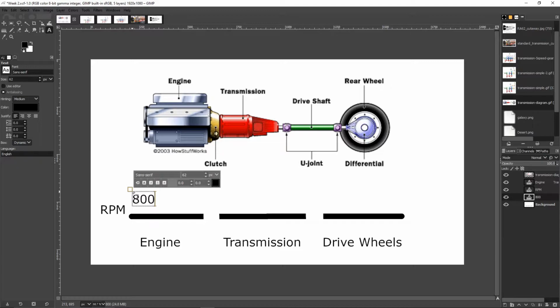And we'll use something fancy, a Honda engine that goes to 9,000 RPM. What's going to happen if this engine RPM exceeds 9,000 RPM? Well, bad things are going to happen. The older engines that did not have a rev limiter, if it was allowed to exceed whatever RPM and it was carbureted, then we'd run into a lean condition. And you guys remember from engine performance that lean is very dangerous. If the engine runs lean, it could detonate and explode.